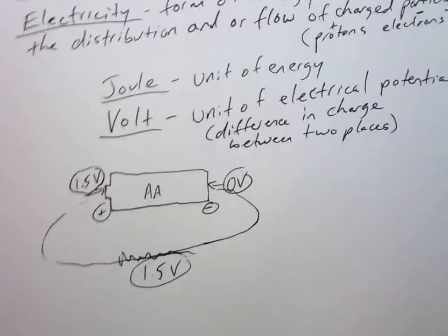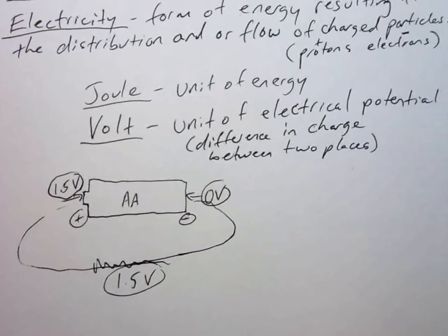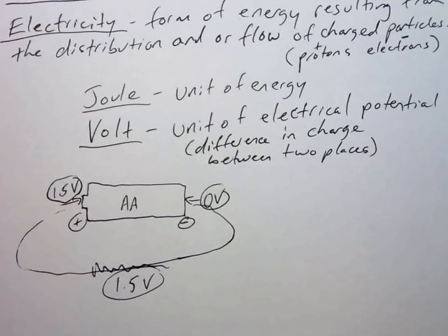Now, it's a little bit different on rechargeable batteries. In fact, rechargeable batteries, for the most part, actually can't get to 1.5 volts, which is why some appliances or some tools say do not use rechargeable batteries for this, because they can only reach 1.3 volts each. But it really doesn't make a ton of difference for most of the stuff you're going to run.